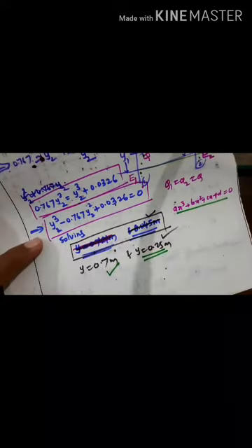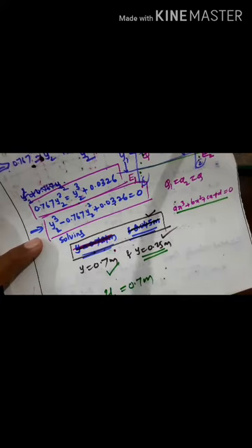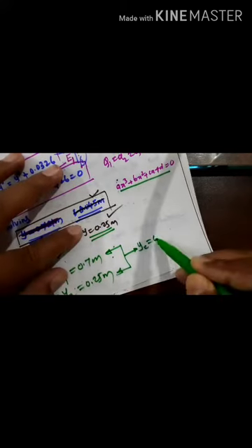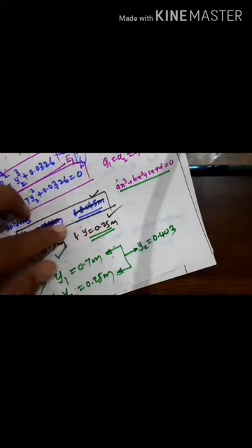So the discharge Q given here can pass at two alternate depths: y1 is 0.7 meter and the other depth y2 is 0.25 meter. You can compare these depths with the critical depth yc, which we already calculated as 0.403.